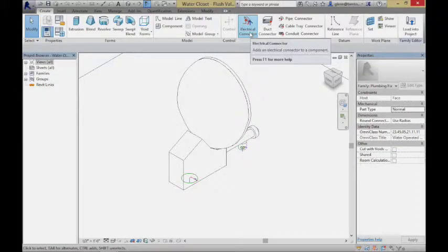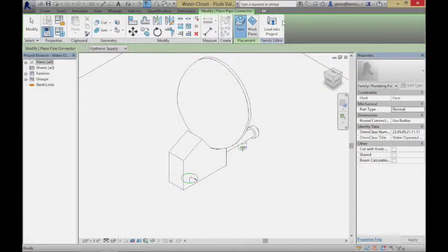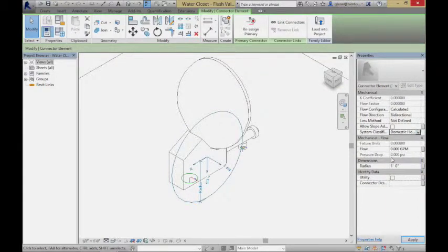So in terms of trying to put together these connectors, let me, for example, say there's going to be a pipe connector to this. I'll put it on the face of something. Yeah, I put a pipe connector. It doesn't make sense to put another one there, but just so you have a sense that I did put one there. You can get a category, for example, if I wanted there to be a hot water connector and a size to that.